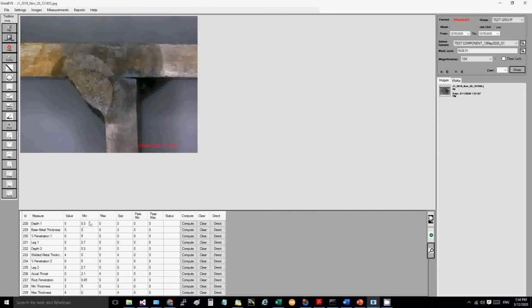So when rule 2 is selected, you can also see the specifications or the cutoff values which were calculated by the system in the background. These values were calculated by the system in the background. The rules were selected by the system automatically depending on your entry criteria. Now if I change it, you see values got changed because in rule 2 my cutoff was 20% of minimum sheet thickness. So 20% of 4 is 0.8. This is 70% of minimum sheet thickness. So all these values got updated accordingly.